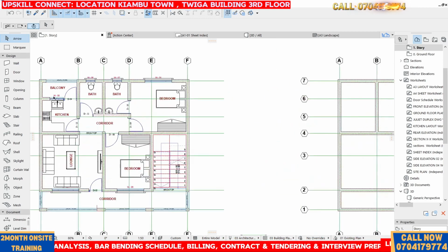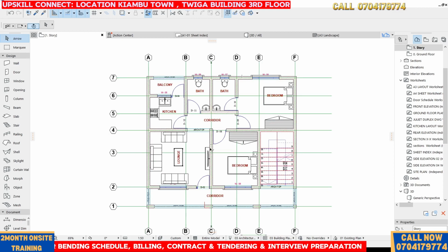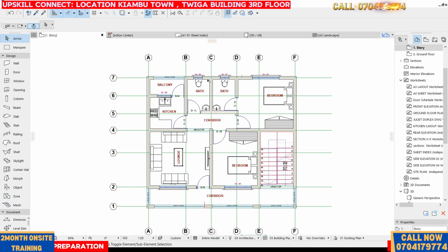Remember guys that some of these are partition walls. They're not necessarily load bearing. For example, even this one might not be load bearing, but because we want to have this beam coming all across and also one coming straight through, because here we are going to introduce a column, and probably here we have a column, so that we can connect the two columns with a beam, right?